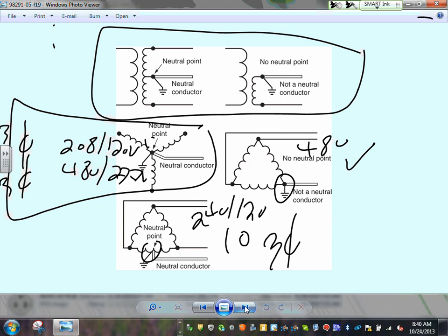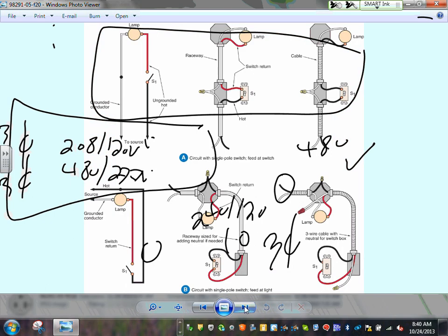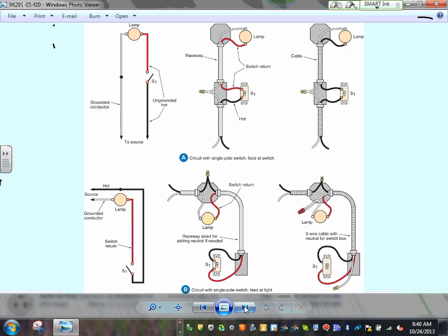So these are the systems that we use. The most common one is a 4-wire. We talked about this one, guys, and all the requirements for this. So, Adam, I know you guys are not designed right now to be an electrician. I want you to fully understand, when we do takeoff in the spring, I'm going to look you in the eye and you're going to come here and do takeoff. And when you do takeoff, you're going to decide how many conductors are going to be in this wire. I know you guys are not an electrician, but you will need to know how it wires.